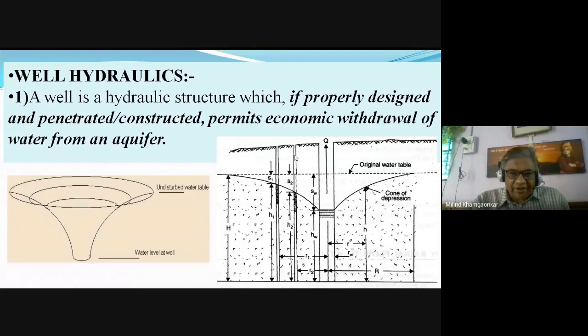On the left side there are two sample wells, you can say imaginary wells, to understand the concept. The two wells are there, very small wells on the left side. One well is at a distance of radius r1 from the center of the main well, r1 you can see here, which has the depth of water h1 in the unconfined aquifer.